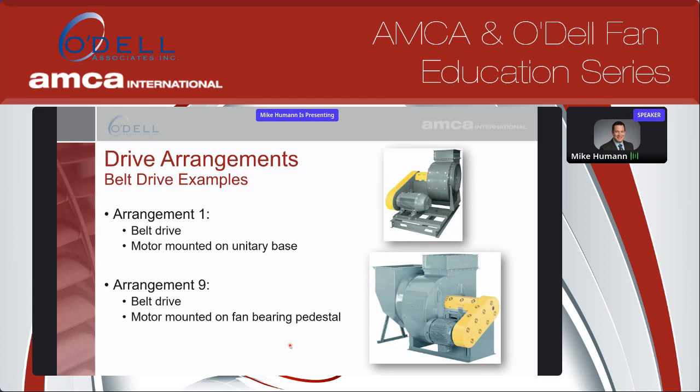So the arrangement 9 is a little bit more compact. You see that motor is mounted on that bearing pedestal. That does make for some difficulty sometimes when it comes to maintaining. If you do need to remove that motor, it can be a little awkward, especially when you get to large motors. Smaller motors, it's not a problem, but it is just a different type of belt drive fan with a smaller footprint.